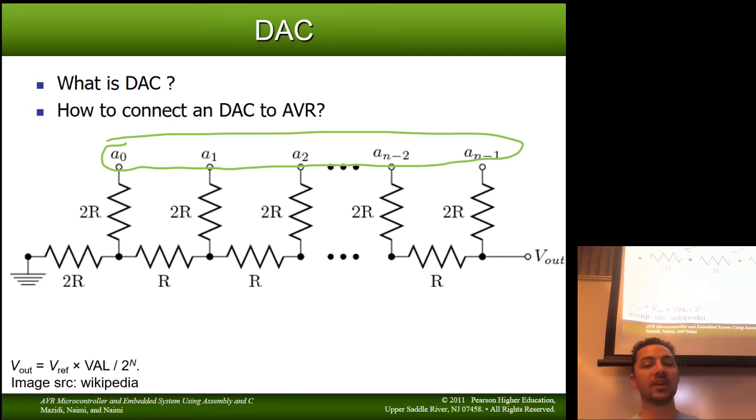Depending on which of these you tied high and low, in this configuration, you will get a proportional response for the voltage output. It's not going to be super accurate, but if you're going to be buffering this, it's going to be pretty handy. And it's relatively simple. You can do this with a bill of materials of one resistor. If you need an R2R ladder, you can use just 100 ohm resistors or just 1K ohm resistors.